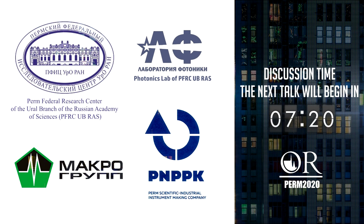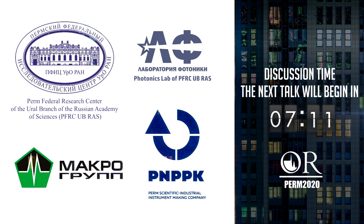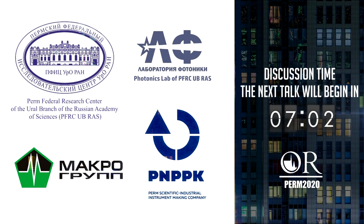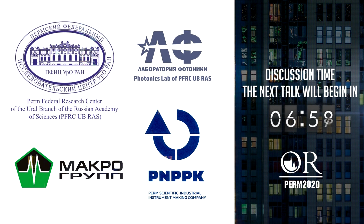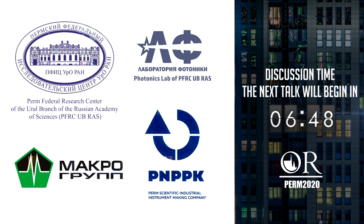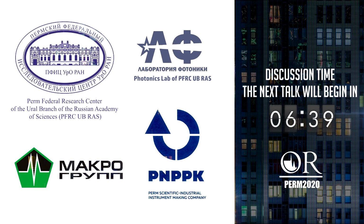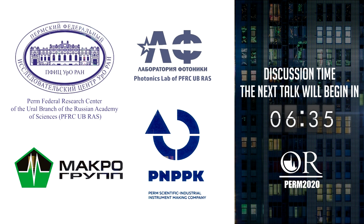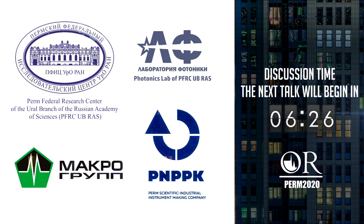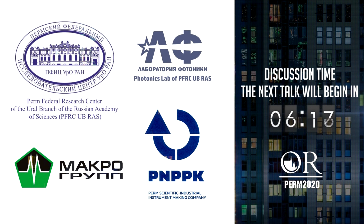Well, again, it is very good that we have some time for the translation. The first question, a very popular question from those who prefer distributed systems: what advantages of a quasi-distributed system could you mention? And the answer was that for hydroacoustics and geological studies, it is much easier to find the distance between the phase centers in a hydrophone, which could ease the data processing. And the second question was, you interrogate the reference channel as well. So if you exclude or change one of your sensors, does this mean that you need to recalibrate or even change the reference channel? And the answer was that this application allows obtaining an individual calibration signal for each sensor. So if it is removed or even changed, it's not a problem for such a system.